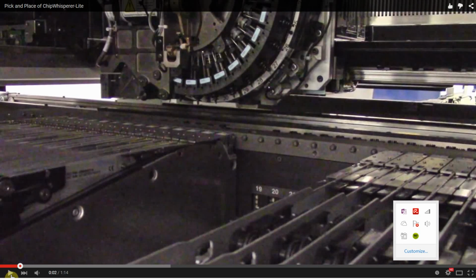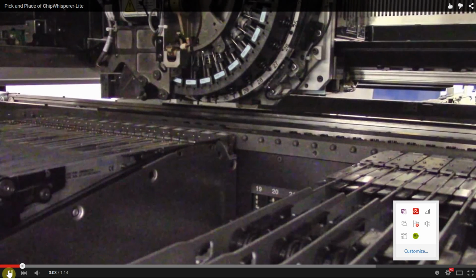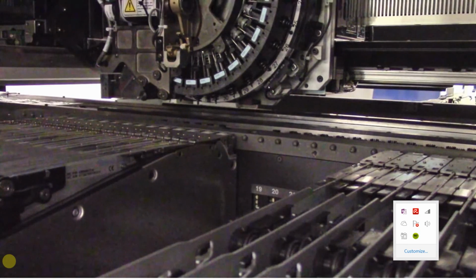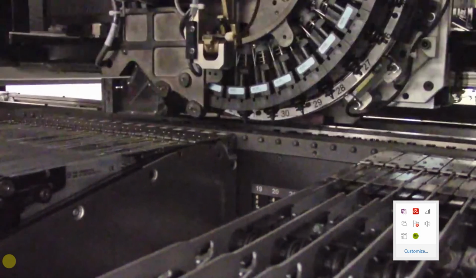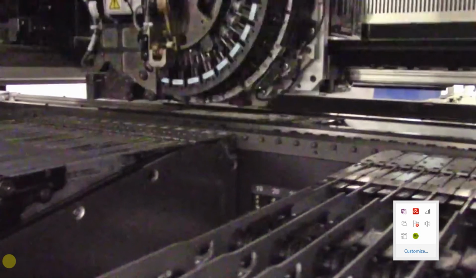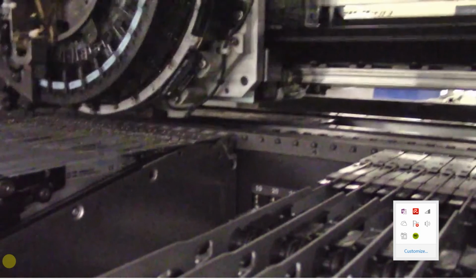So you'll see this head. It has a whole bunch of, you can see some of the numbers there, 25, 26, etc. Those are actually pick and place heads, so they're little vacuum nozzles effectively. You can see the tiny nozzles there. Over here, there's a whole bunch of what are known as feeders. So this just has a whole bunch of parts set up. So it'll just go along, pick up parts, and then put them down on the board. And it takes, like, you'll see 30 seconds. It's building 4 at a time. So it's just going along, picking up 20 parts or so. And then you can see it just shoving it down right on the board. This is real time? This is real time, yeah.